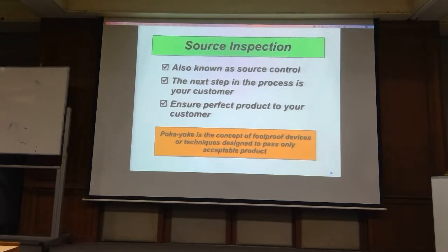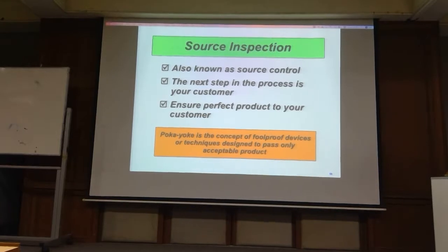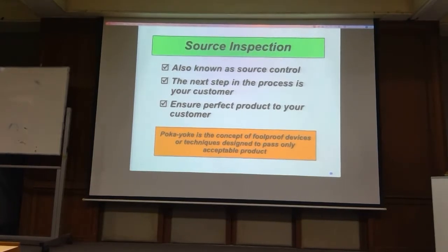A very easy poka-yoke is to put all the bolts in a tray right out in front of you before you make the assembly. And when you finish the assembly, before you send it to another station, just look at the tray. Do you still have a bolt left or not? So this is a very simple poka-yoke.